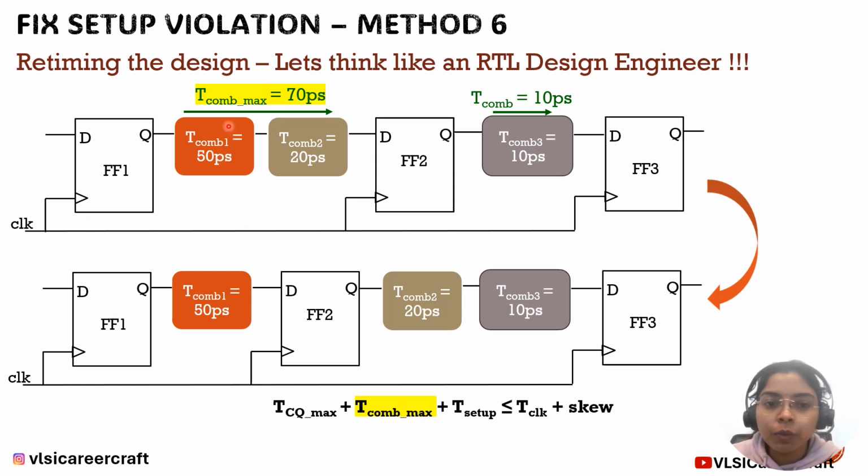So what will I do? I'll push this combinational logic 2 block into the next pipeline stage and keep this combinational logic 1 here in the first stage. What will it do? It will make the combinational delay max 50 picoseconds now, which was 70 initially.